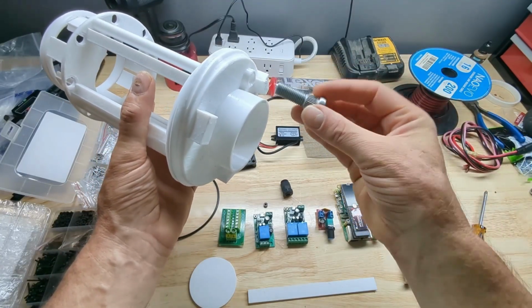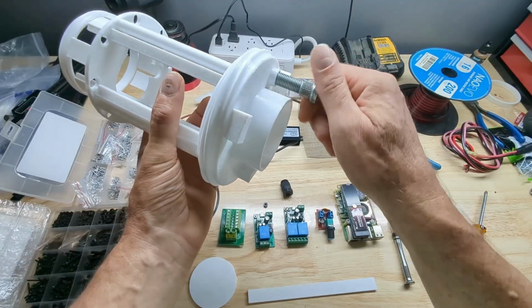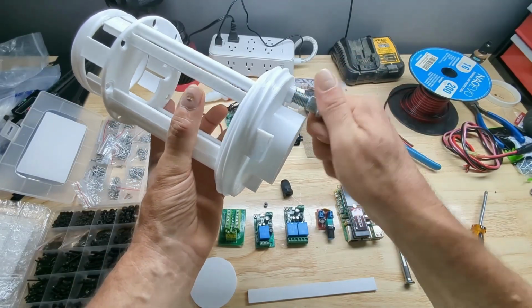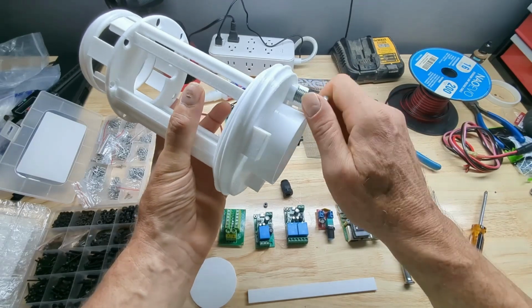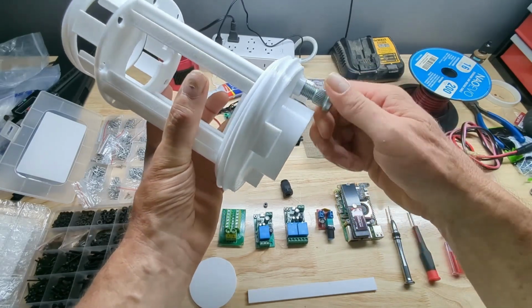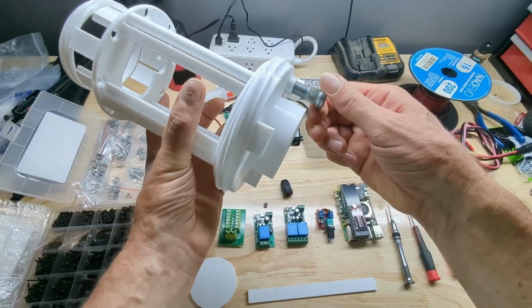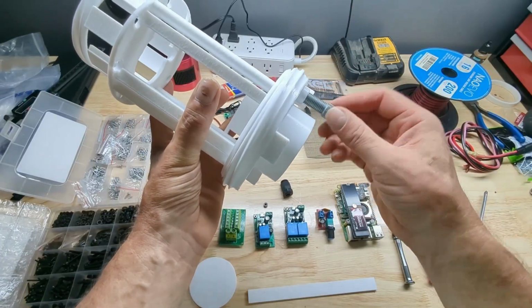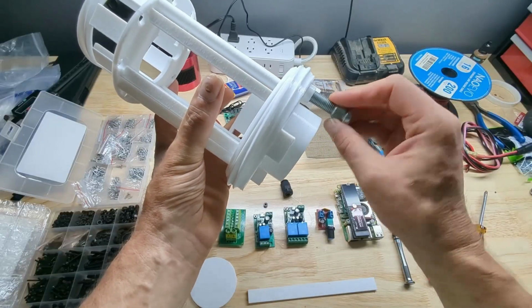So if you have a steel bolt, you can just thread that in there. It just cleans up the threads. That's all we're doing with this bolt, is just making sure those threads are good all the way through. And this way, when you put your wire gland in for your power supply wire, it'll be nice and clean, and that will thread right in. So that's all this bolt is for. And it's a 12 millimeter with a 1.5 millimeter pitch.